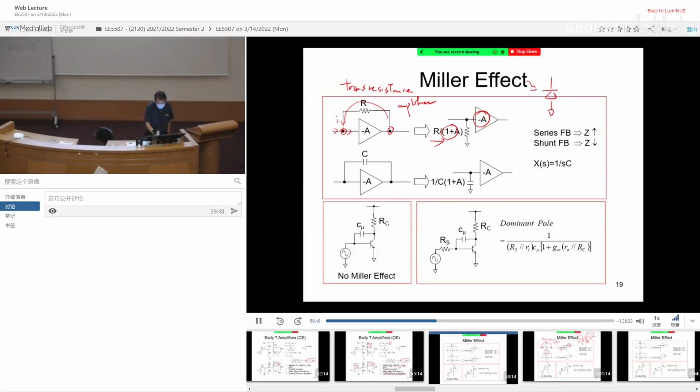photodiode. The light shines on it, and it will start to generate current flowing through. Now, if you have this kind of transimpedance amplifier, you are reducing the equivalent resistance looking into it. So let's say there are some other things connected over here, you know current prefers to flow to the smaller resistance. Am I right? But because of this, the transresistance amplifier is presenting R over 1 plus A. It's making the resistance A times smaller.